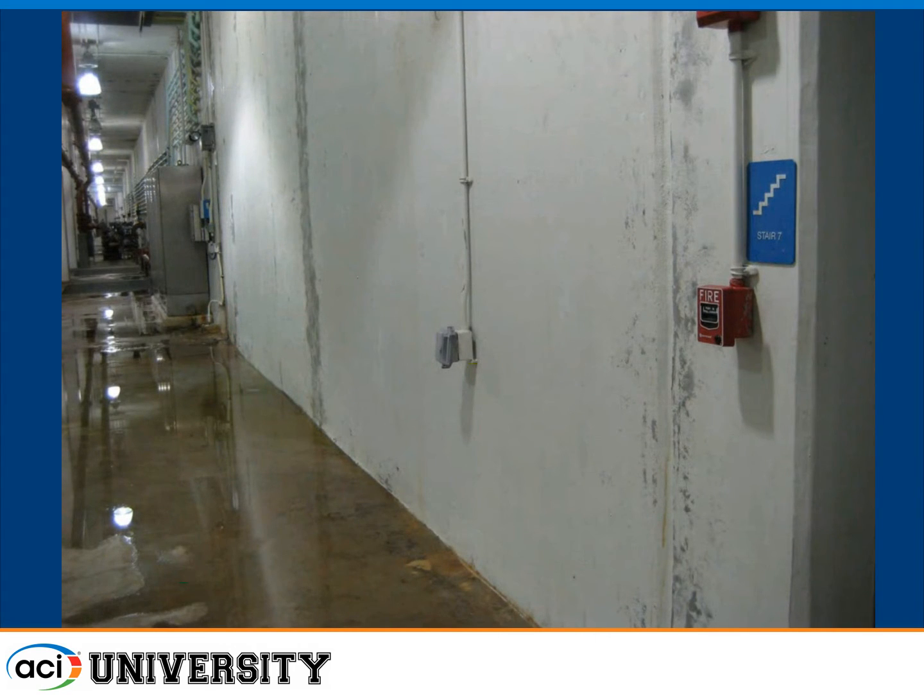This is another tank. This is a gallery in between, and it's kind of like a little swimming pool here because this tank was actually part of it was designed per ACI 318 instead of 350. And so it cracked and it leaked, and the owner doesn't like that. So our specification, our code deals specifically with the details that need to be done to make the structure relatively durable for the exposure conditions and relatively small, at least small cracks so that we don't have major leakage.